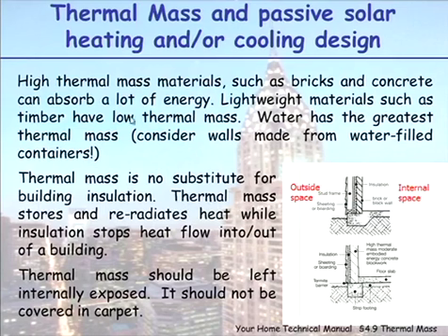Lightweight materials such as timber have low thermal mass, so they don't absorb as much heat into the building. Water actually has the greatest thermal mass. So how about making walls from water-filled containers? Have a think about it. Okay? Thermal mass is no substitute for insulation, so I'm not talking about insulating the building.